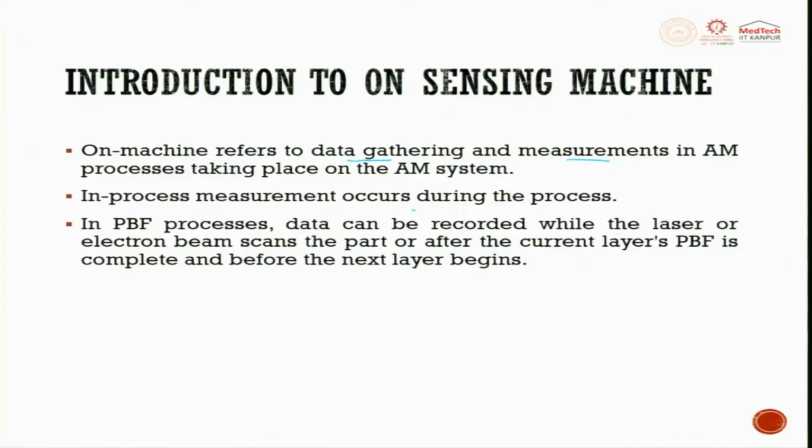For example, if there is a thin layer getting selectively sintered using the laser beam powder bed fusion method, you might sense the residual stress. How is it done? It is a question. Today, do we have a technology? We have an indirect technology to measure residual stress. So, residual stress can be measured, and based upon the residual stress, the next layer thickness or the laser power can be tweaked to meet the requirements.